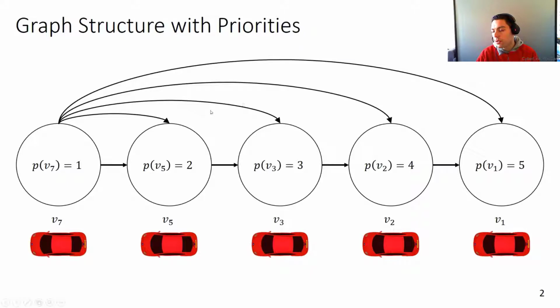And we did that because, if vehicle 2 gets half a meter from vehicle 1, okay, that's not a good example. When vehicle 3 gets the reference that it needs to be half a meter behind vehicle 2, but vehicle 2 is not half a meter behind the leader, then we thought this one should ideally have a reference of being 1 meter behind the leader, despite the location of the second vehicle in the row. So that's why we decided to add this communication layer.